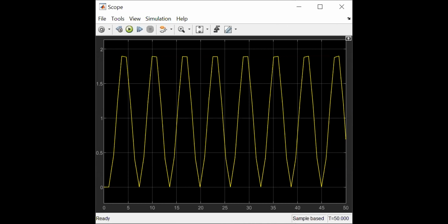There are slight oscillations because of the poles that we have in the system. We have plus minus i as poles. We are on the purely imaginary axis. So that's why you would see the ramp output with a sinusoid.